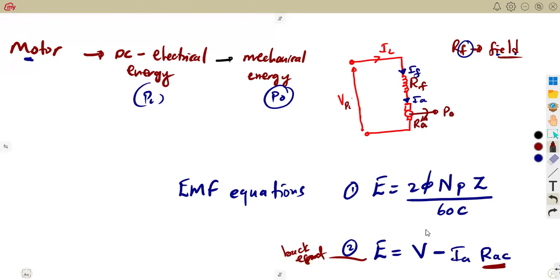So you need as your basics to understand the types of circuits that you're given, because you need to know the resistance of the armature circuit. Like in a series consideration like this one, where the armature current is flowing, that is where we have this resistance of the armature circuit. So you consider that of the armature and that of the field together. Meaning to say, if it was like this, the resistance of the armature circuit was going to be what? Ra plus Rf.